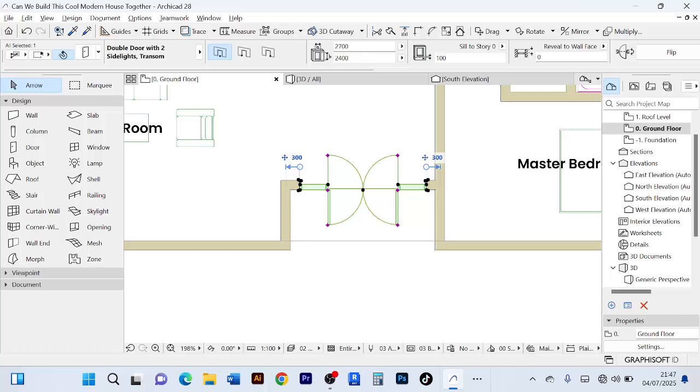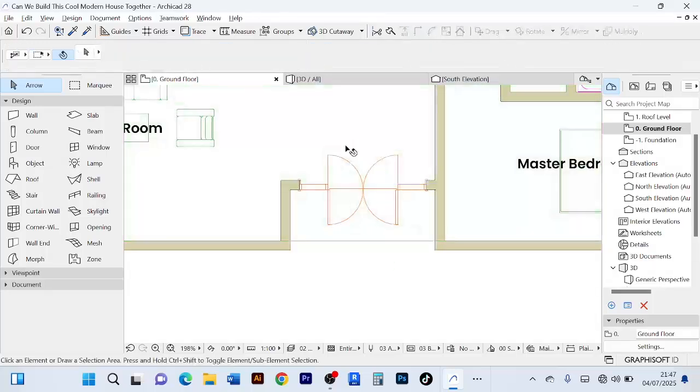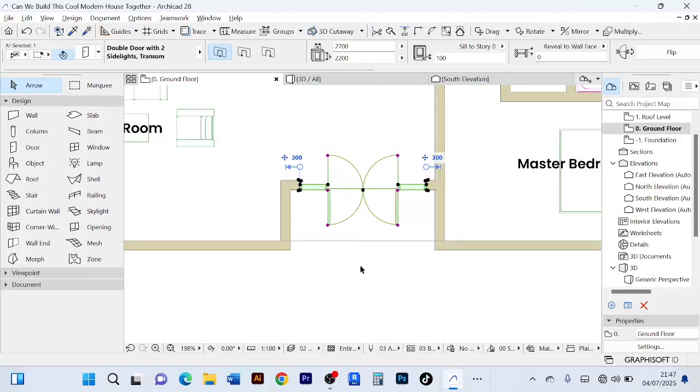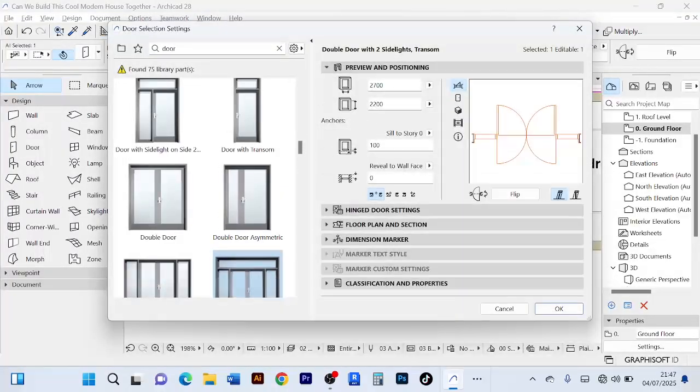Then when you come to the settings, you see here this door is 2.4. You can control that size. Let's say we want it 2.2 meters wide. Just enter and it will reduce the size of the door, just like that. Then of course when you press Control T, that's exactly where it will take us to the measurement, so you can still control here. Then the head height, this is the width actually, then this is the height. Now the height, we have to control the height.